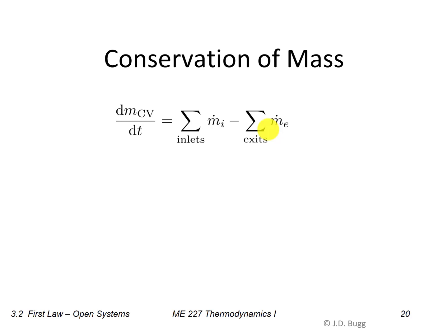Now the last thing I want to talk about here is a connection between mass flow rate, and that could be either one of these things, whether we're looking at an inlet or an exit, doesn't matter for this discussion. So the connection between mass flow rate and three other characteristics of those inlets and exits. So m dot is equal to A times V over the specific volume.